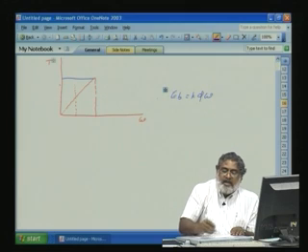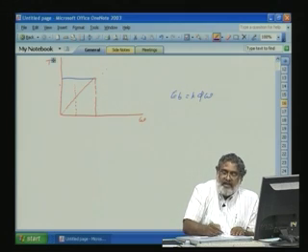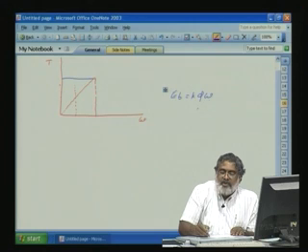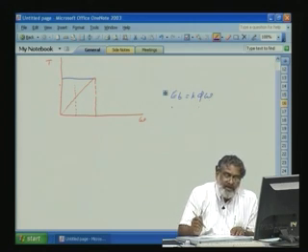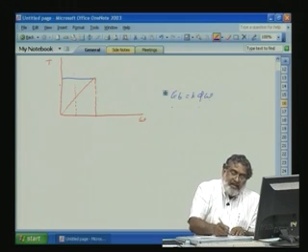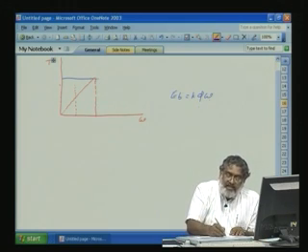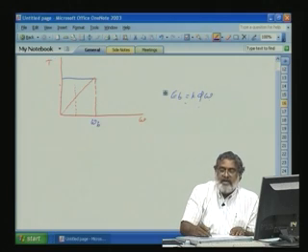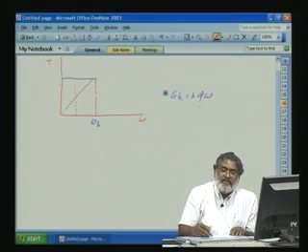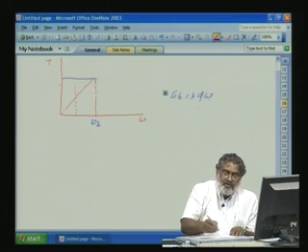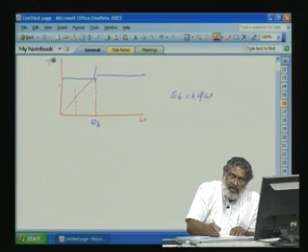At this point, if you want to increase the speed again, we can reduce phi omega such that EB is constant, at the maximum rated value. From this region, above this region, this is called omega base speed. Since EB is constant, that means V is also constant, and the current is also constant depending on the torque. We will reach the maximum power region, but torque is variable. So from here onwards, this is called the constant power region.